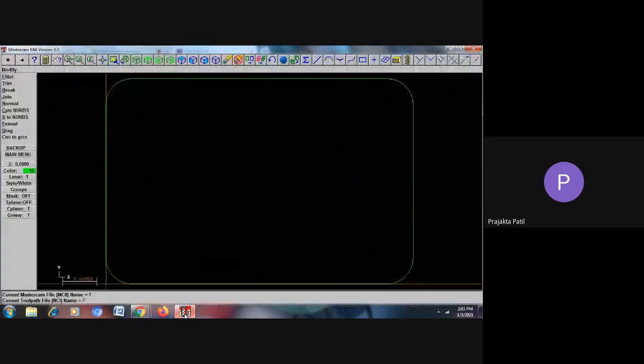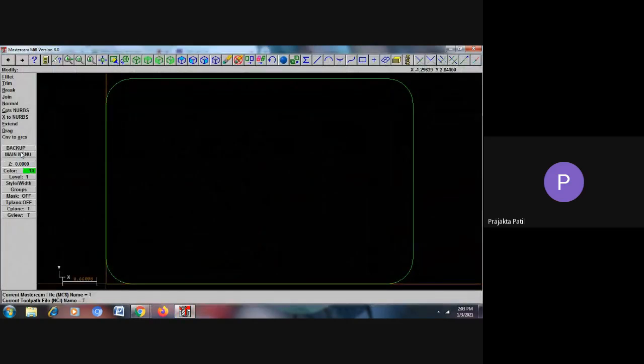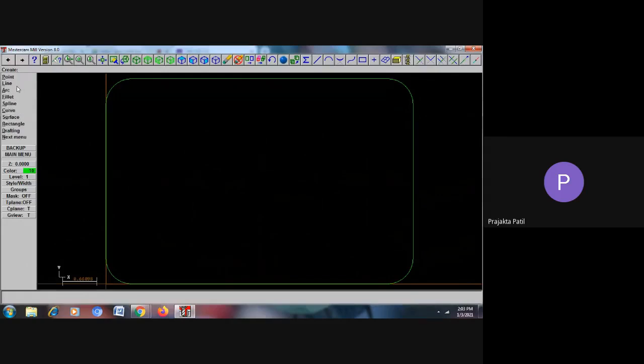So we will go to the main menu and say create point. You want to give the position, so say position. What is the position? It is the center of this arc. So it has taken the center of this arc. Likewise, you can again click on center, click on the arc, and you get the center. So these are the 4 points where the drilling operation needs to be performed. Go back to the main menu. Let's go to the next step.